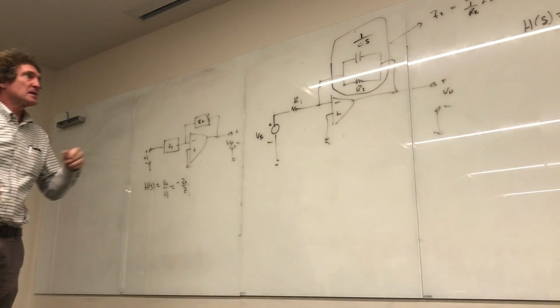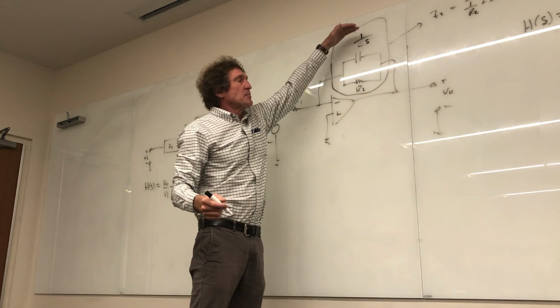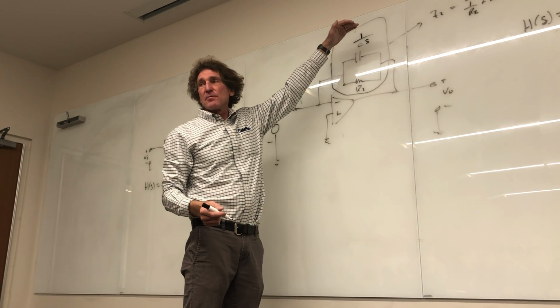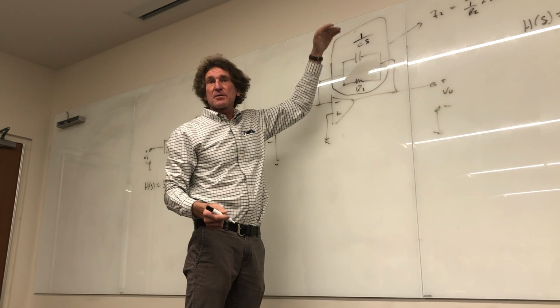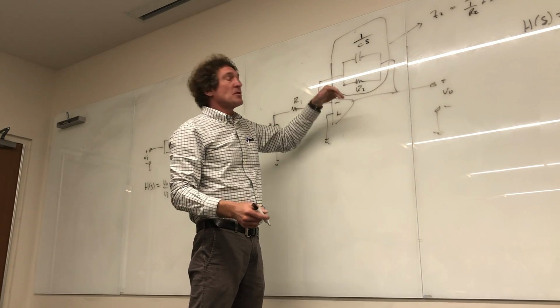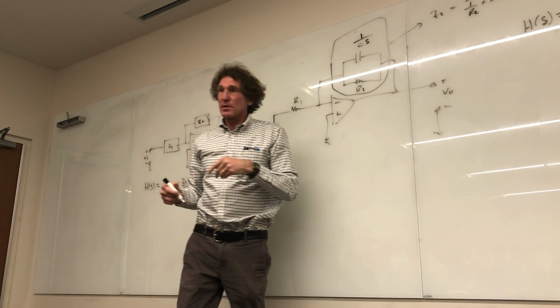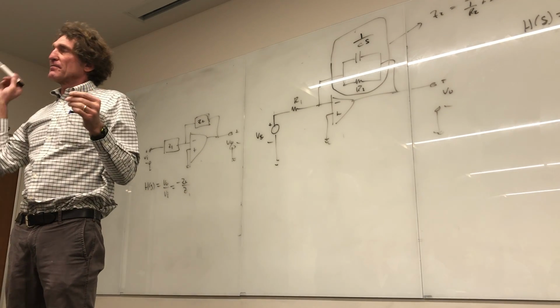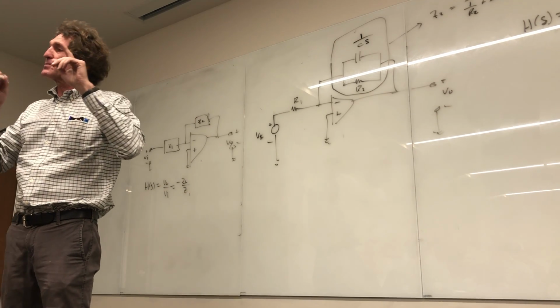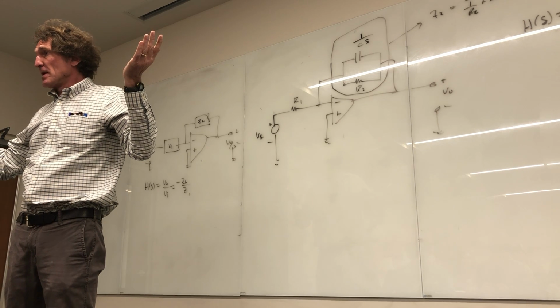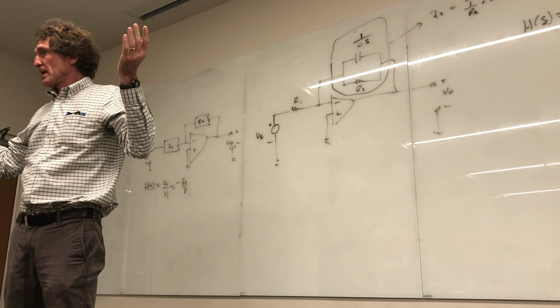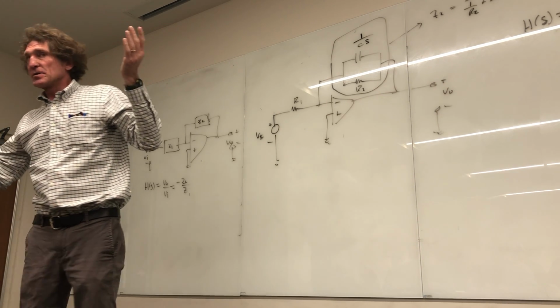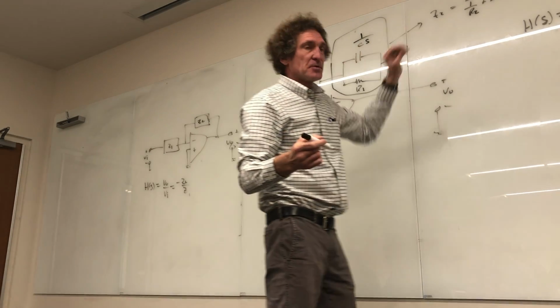And I do it this way because it doesn't have to be 2. I could put 3 here very easily. As a matter of fact, I will on a test probably. It will be an inductor, capacitor, and resistor. Then it's 1 over the first plus 1 over the second plus 1 over the third. Do y'all understand that? Now if you just do the cross, first impedance times second over first plus second, it works out the same, but there's a little more math involved. Everybody got this? So just leave that there as Z2.